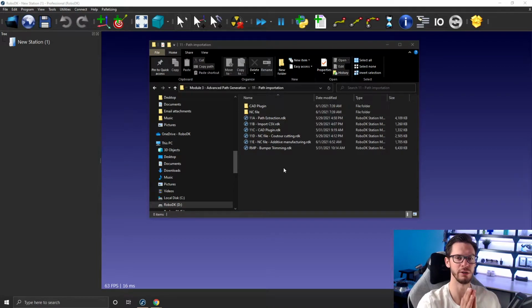It's either a machining or cutting path generally, but it can also be a 3D printing path, as they use the same model of program in the background, or way of writing down the program, for those applications. This kind of file can be generated from a CAM system, CAM for computer aided manufacturing, so machining software. You can think of Mastercam, AlphaCam, PowerMill, Catia does some, Fusion does some, etc. And in terms of 3D printing, the NC file is generated by a slicer.